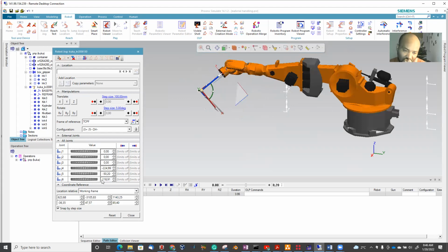So this time, if I know the joint variables for all, but I do not know where the robot TCP should be, then I could use forward kinematics in order to calculate or compute the end effector position, or the Cartesian space. But the other case is if you know only the paths.